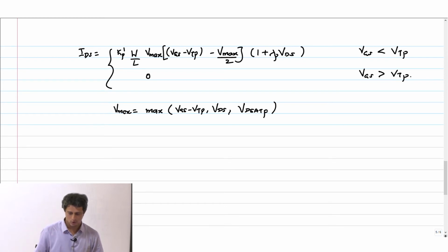So what we will do now is to simply compare what the sign of each of these parameters should be. We had 5 parameters that defined the level 1 spice model for the NMOS transistor. We have similar 5 parameters here. I'll write that on one side: K prime, then VD sat, then lambda, then VT naught and gamma.